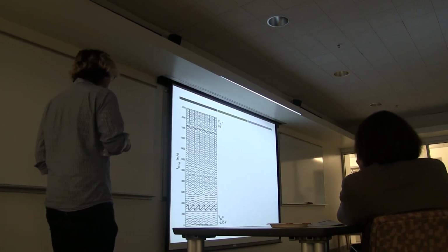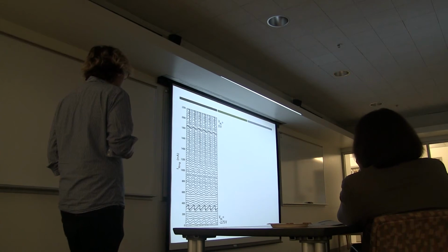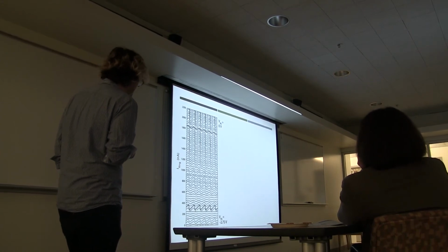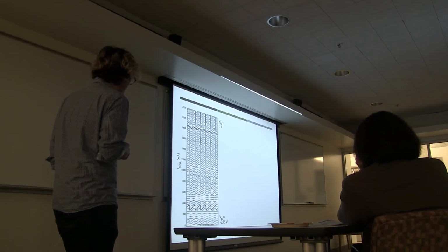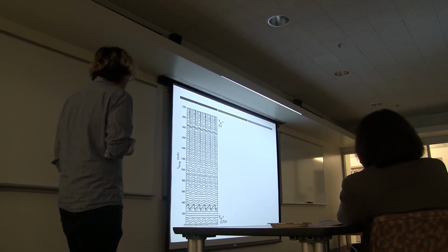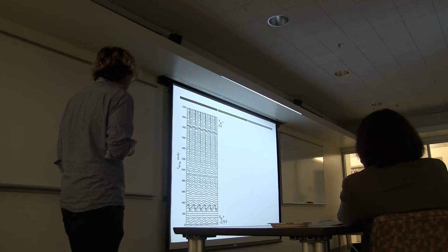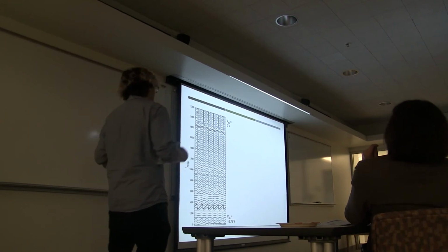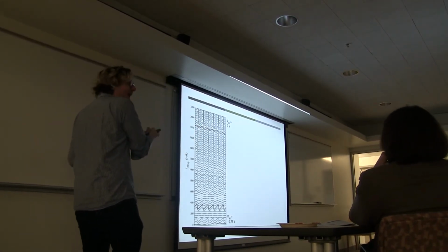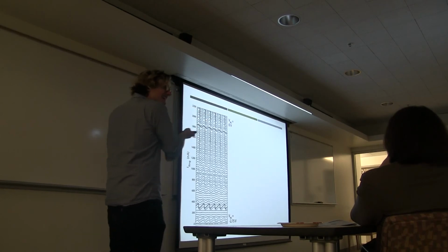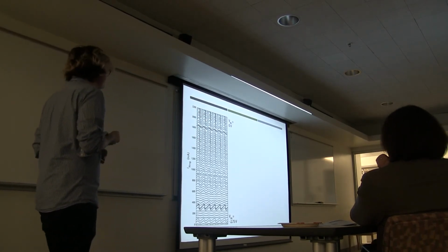As you can see, especially at low gate voltages, there are strong amplitude fluctuations, but there are also very strong shape fluctuations. Here we have one that's not so forward skewed, or this one maybe, and then only 2 gate voltages away is the most forward skewed current phase relation we see at any gate voltage. So both the shape and the amplitude of the current phase relation are changing really quickly and wildly as we tune the back gate voltage.